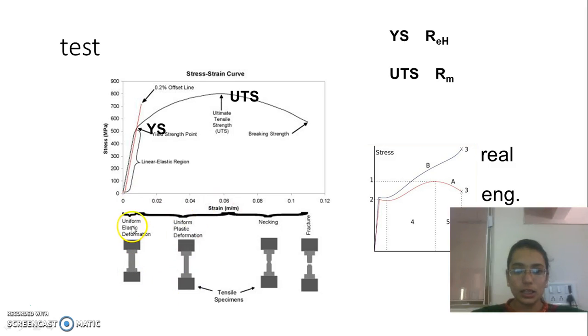If the equipment we are considering shows uniform plastic deformation, necking, fractures. This curve is showing the different stress-strain. Here you can say that if we are considering any equipment, from 0 to 500 position, it will continuously increase. That is the linear straight region, and at the 500 point, it is the yield point. After that, it will be the curve region, that is the ultimate tensile stress curve, and at the end of this is the breaking point. Here you can say that this is the real curve generated by the stress-strain, and this is the engineering curve generated by the stress-strain of the mechanical equipment of the model.